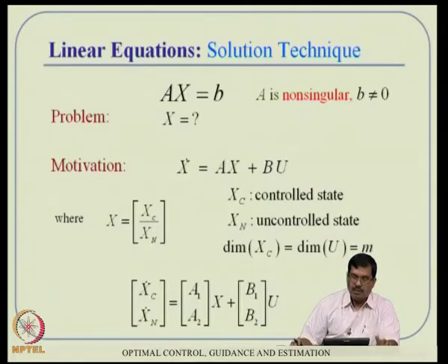If your aircraft flies steady and level, you really require some sort of a trim moment, because remember your CG and CP are not at the same point. That means there is a continuous gravity related and aerodynamic lift related moment which will act on the vehicle.